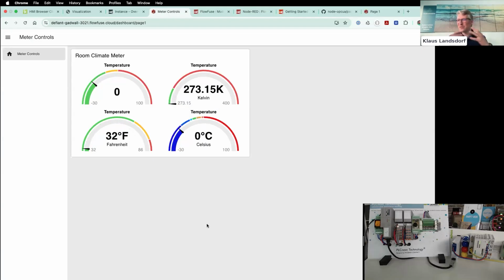Oh, OPC UA is so big, we have so many things in that, our network is going crazy, whatever. But at the end we built really huge systems, bringing everything to OPC UA: the robots, the machines, the lines, everything. And it is really, really fast, and the traffic is absolutely low because we're just exchanging data if it changed. And this is very different to other protocols from my perspective, because at the end you can trust it, because the connectivity will not just break, it will come back. You get all the data as long as you are connected.